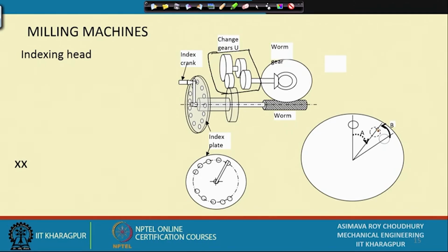And on the milling machine we saw a special type of tool which can be used, which has the conjugate profile of the tooth space. It can remove the tooth spaces one by one. Okay. So, this method is quite versatile, but mind you, for production of accurate gears, this method is not applicable. No, this is generally used for maintenance.